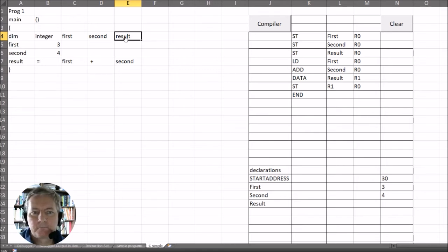So what would happen is whenever we open up the main here, the main is going to give us our start address. This is our directive that tells it the start address for our variables. What that would also do is go in and save the existing values on the registers to somewhere in memory. Usually it would save it to something called a stack, but we've not gone into the stack yet, and we will go into it later. So it would save the values for, say, the 4 registers R0, 1, 2 and 3. It would save them in memory somewhere.